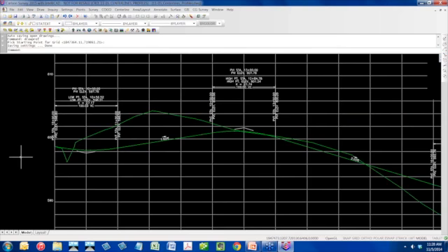So that's all there is to it as far as creating... you see now how to create a profile from a surface, how to just create a generic one or a road profile that you type in. Any profile you've got the data for, you can just go into Input, Edit, create a new file, and enter those in. No questions, Karen?